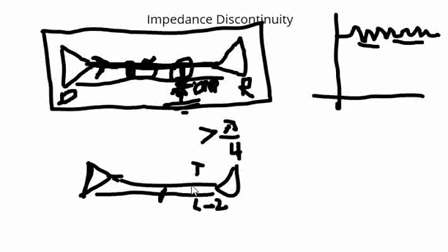When the return signal comes this way, it tries to take a longer route and then passes back to the driver. So this signal is actually unintentionally traveling across the board, which might cause the issues that we are seeing due to discontinuity. That is one of the important parameters which need to be considered. So these are some of the parameters.